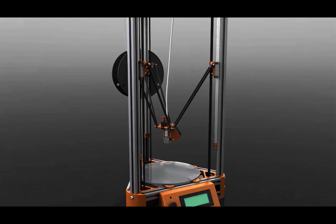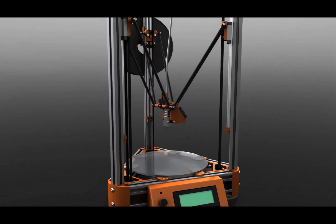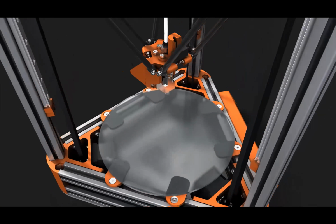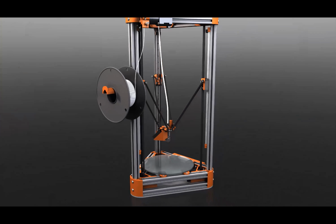Most FDM printers work in a similar way, but the Delta printer has a few key advantages. You may have noticed the Delta doesn't have any motors attached to the print head. Instead, they're hidden down here at the bottom of the printer. This is a big advantage of the Delta design. Some of the heaviest parts in a 3D printer are the motors, and by keeping them static, the print head can move much faster with less chance of mechanical parts flexing due to shifts in momentum.